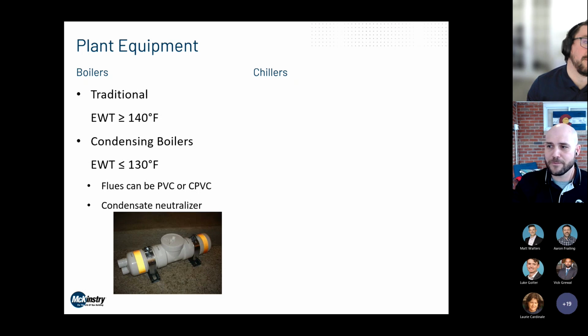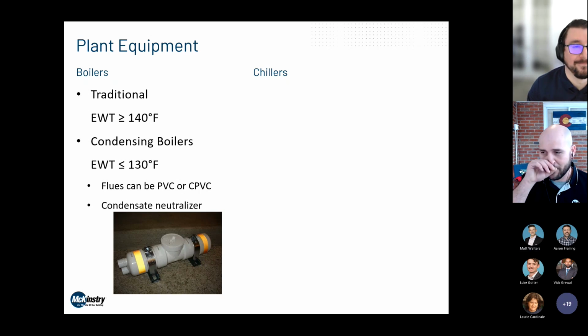Then it ran from the neutralizer into a cast iron pipe. If and when that thing runs out, and nobody checks or replaces the lime chips in there, then it's going to eat away at that pipe, and it's going to be on the roof of the boiler operator's office, dripping down there, which is terribly inaccessible, really lousy design. Putting it on the wall would have been way better.